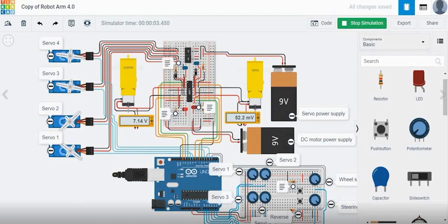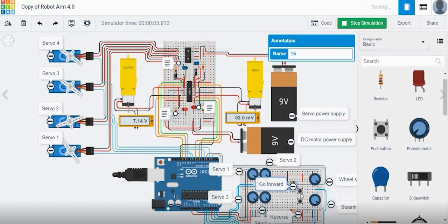So how can we determine the direction of our tire, which gives the forward or backward move? By these two push buttons. If I push this top button, it will give positive RPM, which means our tire moves anti-clockwise and our robot will move forward, and reverse vice versa. So let's see. First I have to turn off this one and turn on this one. It will give negative RPM.